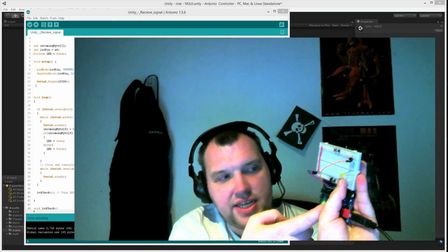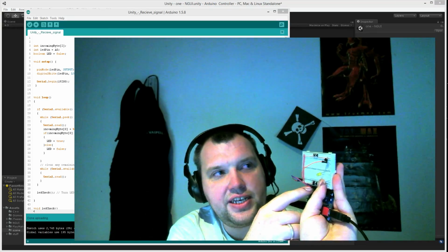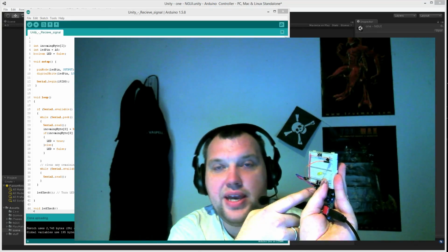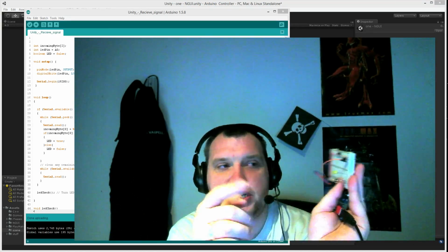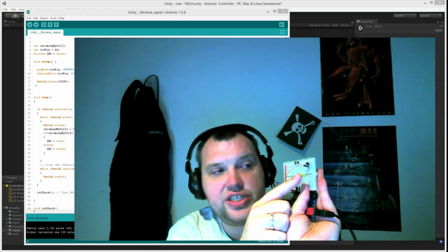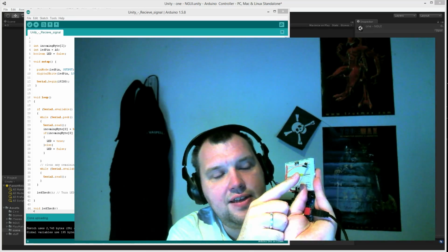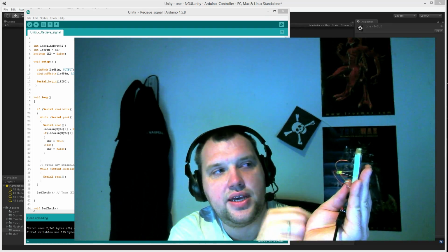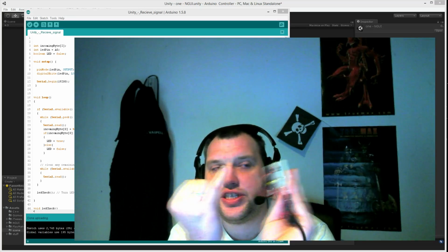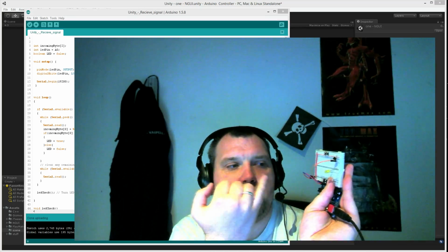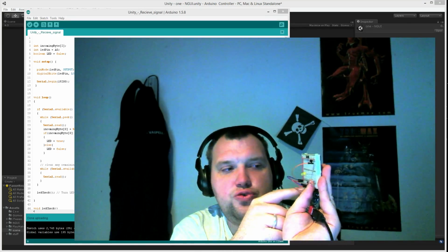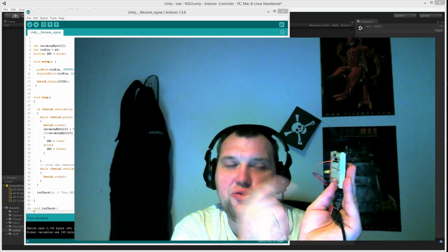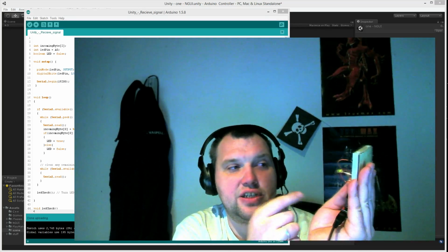My setup is an Arduino Uno. I've got a wire from A0 to a transistor, and that transistor leads out to an LED and a small resistor. The reason I'm using a transistor is because I found powering things through my analog out is not really working very well.